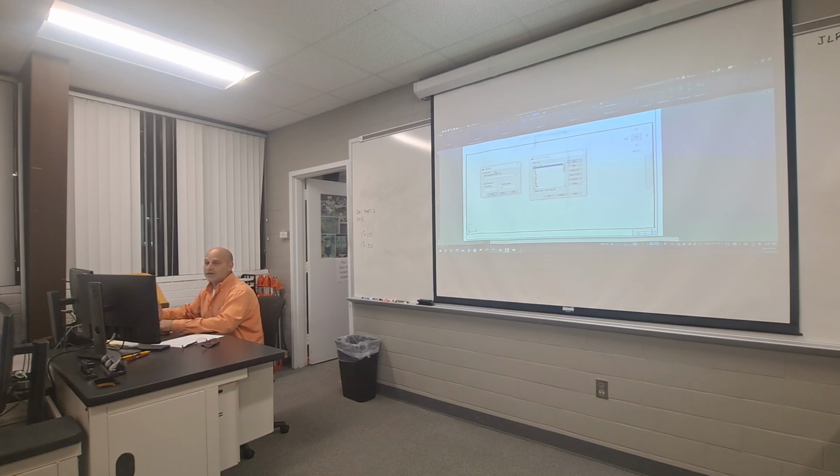Your civil scales in my eyes should be the same. So they all start with 1 inch equals. This one that I'm doing here is 1 inch equals 10 feet. So I type that name in. Maybe you say, well, I'm lazy, Mr. P, I'm just gonna put 10 feet in there. I don't care, I'm not gonna be checking that. What I'm gonna be checking is when you send something to the printer back there and you tell me it's scaled to 1 inch equals 10 feet, if it doesn't look right, I'm gonna put one of my scales on there, and I'm gonna check it. So 1 inch equals 10 feet is my name.